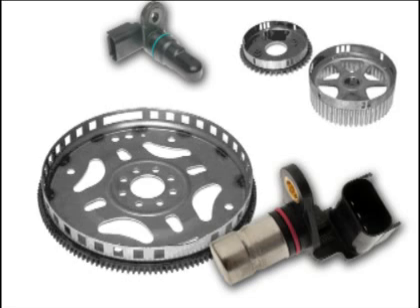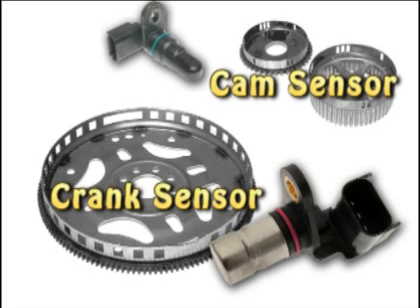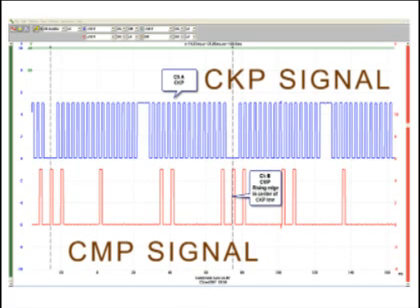The powertrain control module uses two inputs that it relies on for ignition trigger. The basic inputs are crank sensor and cam sensor. The cam sensor and crank sensor must generate the correct waveform in order to correctly control timing. In the previous years, the crank sensor and cam sensor had to be in synchronization for the PCM to turn on the auto shutdown relay and power up the ignition coil.